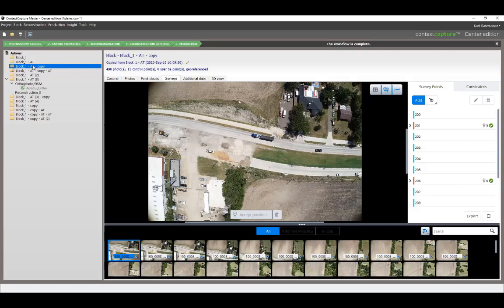So all those accuracies aren't really there with a regular drone. Now, if you're going to use an RTK ground device where you're getting your control points, you're then going to do a post process. So you're going to make sure you lock in that control. Some of those things, like if you're using aero targets, propeller targets, it may go out to a website or out to the cloud and process the coordinate system that you're working with.